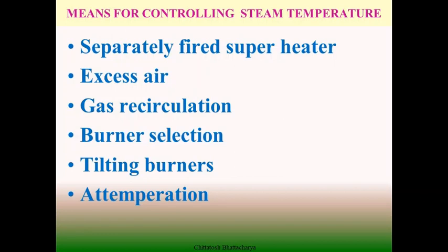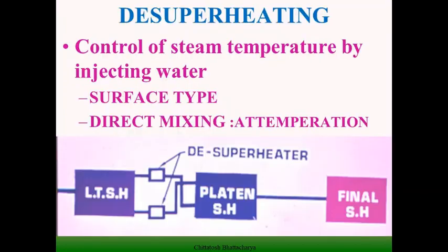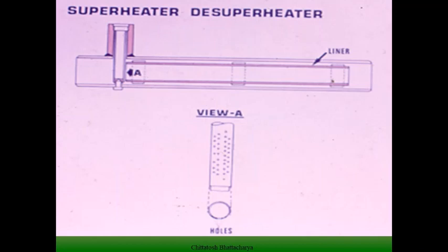In case of a mixing type arrangement of attemperation, we have to regulate the purity or quality of water we are using for spraying. It must have higher pressure than the steam pressure where it is getting mixed, and temperature should be at the saturation level, so that we should not get steam within the steam.